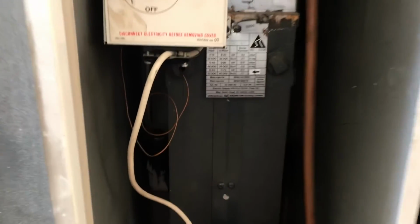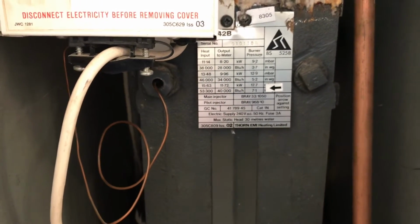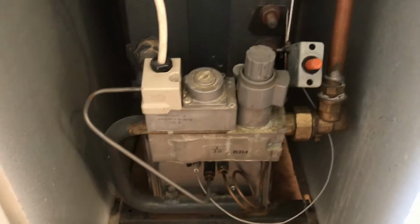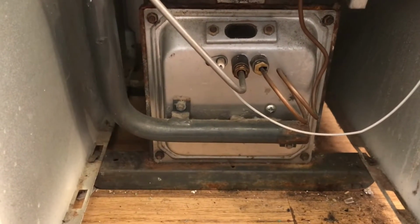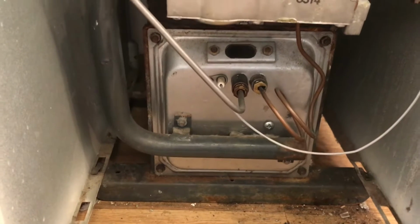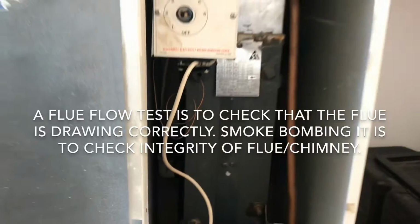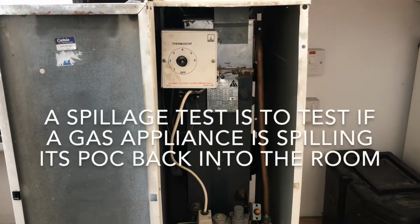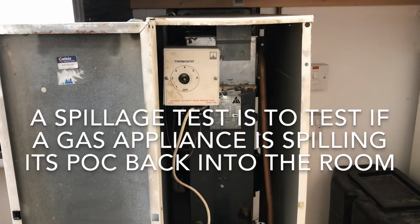So again, if we look at this boiler, it's range rated. Yep, so you can see it's range rated. It's got the same controls, the same gas valve, the same igniter, the same type of burner. The only difference is now its air is coming from outside rather than inside. So we wouldn't have to do flow test and spillage on this boiler like we would have to do on an open flue appliance. So this is a safer boiler and the next generation. So let's have a look at the flue.